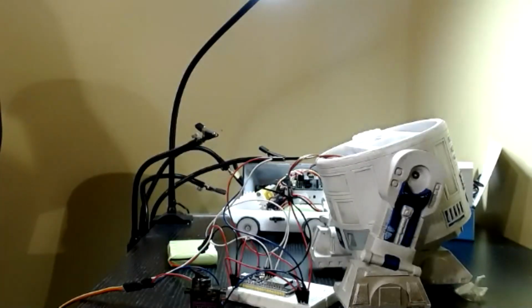I've not so much got a question, I've got a bit of a problem. I've got the ESP and downloaded the libraries. I got it connected to the computer eventually, after I found out the original USB cable I was using is purely power and didn't have a signal line on it. After swapping cables, I managed to upload the ESP Wi-Fi search code to it, and in the serial monitor I could see it giving me local Wi-Fi networks to connect to. So I know that I'm able to talk to the board.